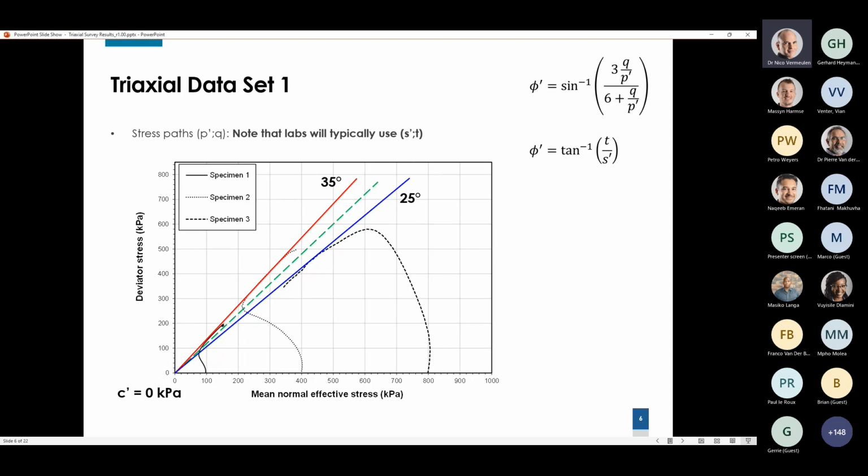at different depths. So we cannot just assume that the 3 samples that were tested in the triaxial represent exactly the same material. And there's a good argument to be made in this case that 2 of these specimens that were prepared from 1 or multiple Shelby tubes represent one type of material, and perhaps the third one represents a more clayey material in that environment. And so we have to be careful to try and always go for the middle ground or for the lower ground. One of the respondents reported a friction angle of 20 degrees.